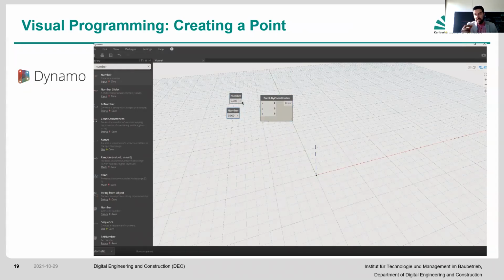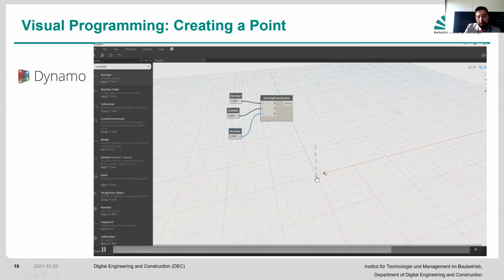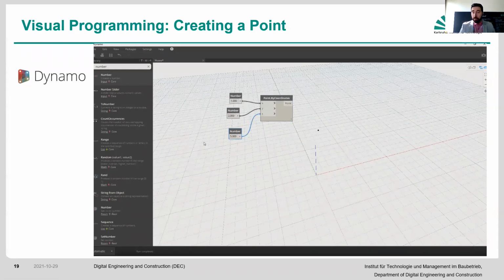You can specify an exact number and assign it to each and every one of these elements. Then of course you can copy that and do the same thing there as well. As you can see, that number is 0, 0, 0. Now you change it to 1, and it jumps to 1 in the X direction. If you do 2 in the Y direction, it jumps to 2 over there. And if it's the Z direction that you change, similarly. So this is how it is.